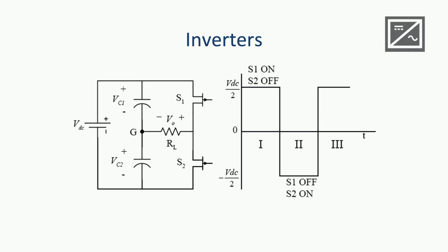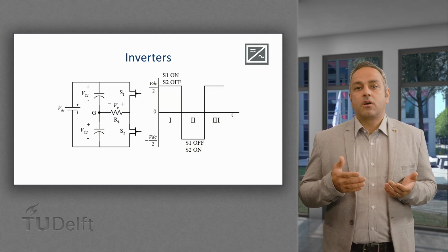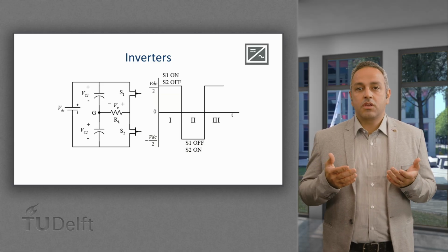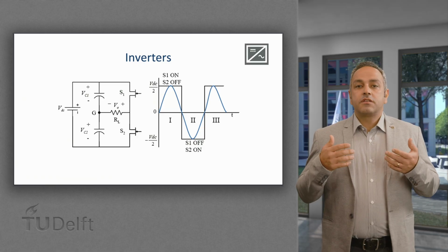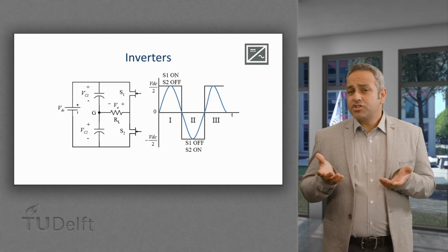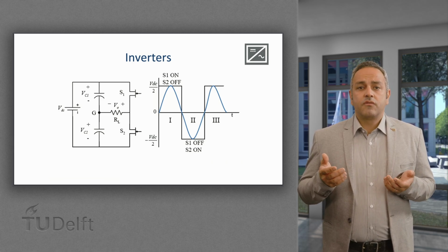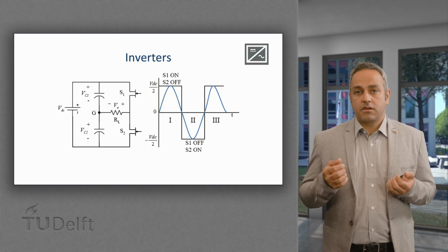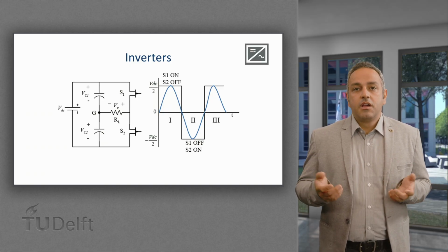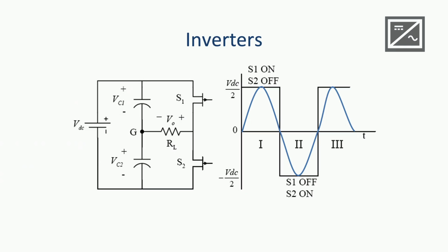When we look at the final output, we can see that the signal has a positive and a negative part, and that it is periodic. Even though this is far from a perfect sinusoidal wave, it resembles it. As I mentioned during the previous lecture, the topology of the circuit inside the power converter will define how close the signal will look to the ideal, in this case, a perfect sine wave. By using more semiconductor devices in more complex topologies, it is possible to obtain better outputs.